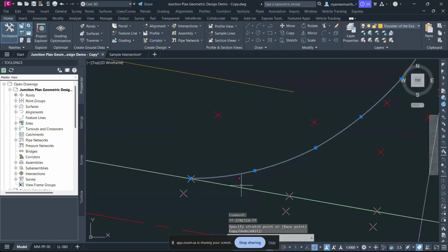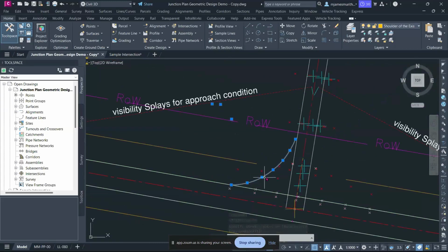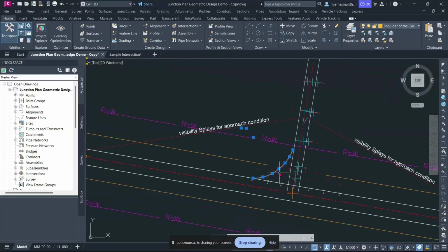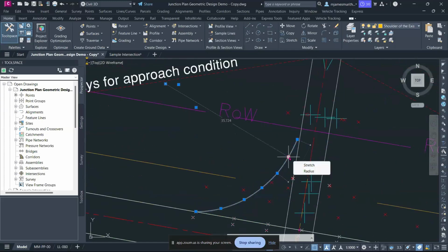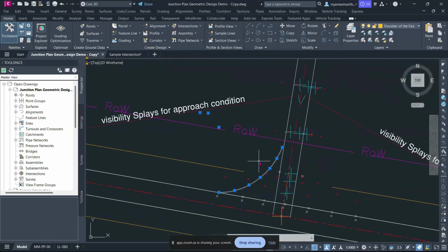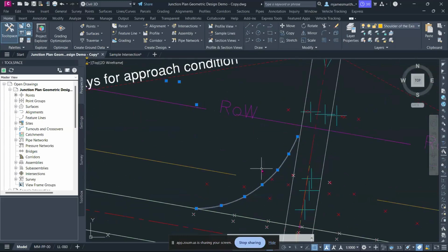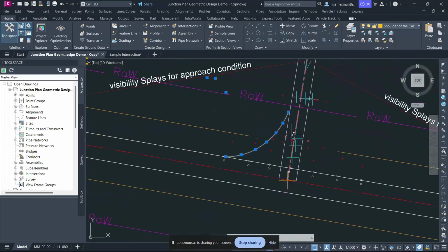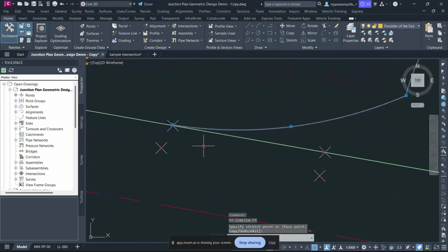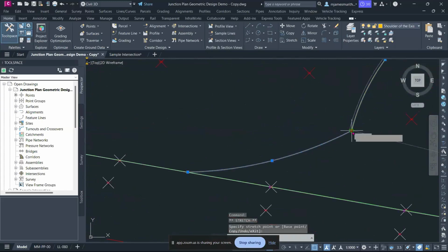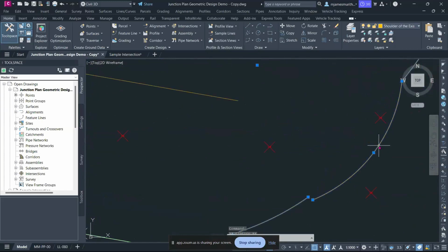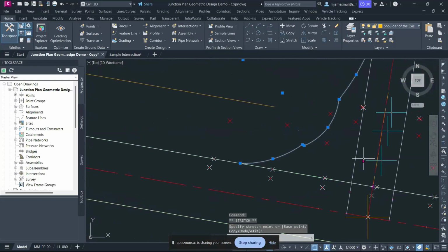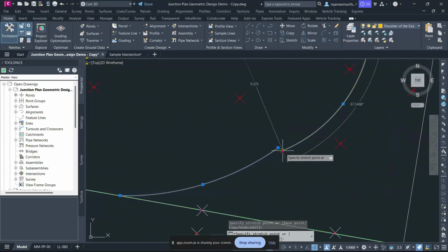So after you've been able to connect these three arcs, you can measure, for example, what is the radius of this one. I can see the radius of this is 25. The radius of this is 33. And then the radius of this one is 35. This is telling me it's an extremely extravagant section. So I can reduce this due to the fact of economy. I don't need to have a radius of 35, 35, 35 at this point. So I'm going to move closer and position these arcs in such a way that I also don't have a too wide section in this case.